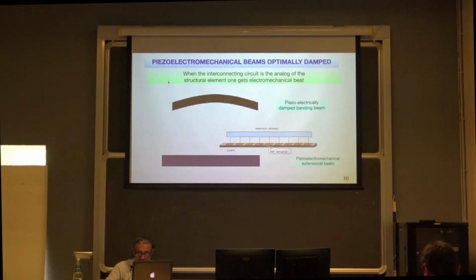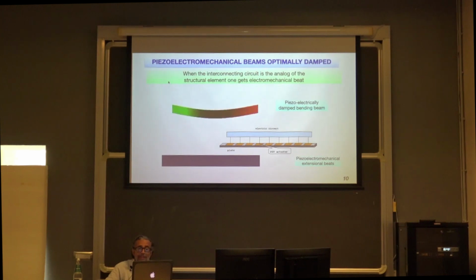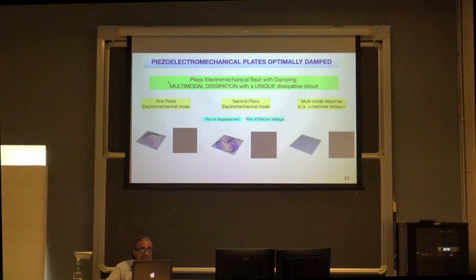And the result is a piezoelectromechanical extensional beam, where you can damp the vibrations of a beam with a unique electric circuit. What is interesting is that you can get multimodal dissipation with a unique dissipative circuit.